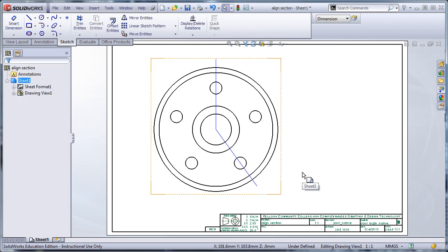Now, as long as I don't touch that line, as long as I don't move this endpoint, I'll be fine. But you've got to make sure your line is perfect and your distance here is perfect, because you can't adjust this once you've deleted that point. You can't move this endpoint up or down at all. It won't stay aligned. So that's a way you can get around it if you have to. Put a point in or a piece of reference geometry, create a relation, then delete the reference geometry, and then don't touch that line.